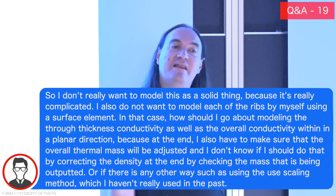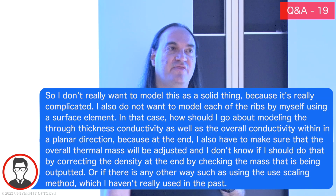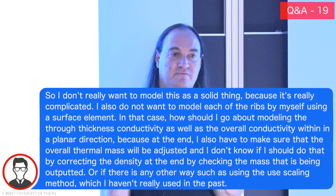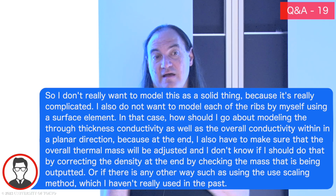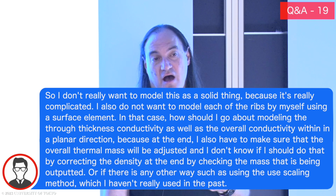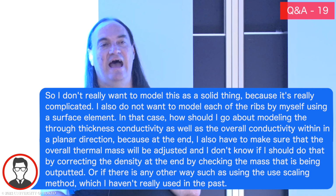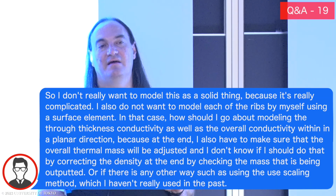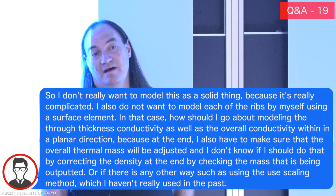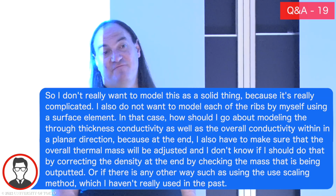But I know we have had pocketed panels like that before and tried to come up with an emissivity factor to account for the deepness of the pockets, and additional conductivity in X and Y for the rib behavior. But it is kind of make a more detailed model and figure out how that relates to my more simplified model and what correction factors I can apply to do that. But I would probably first try to model the ribs if that's not too much to do.